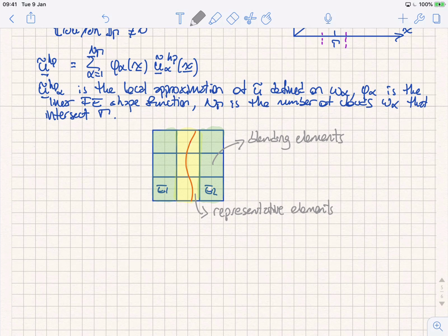That means that it's trying to reproduce some behavior in the representative element that has the discontinuity, but at the same time is connected to another cloud where there is no discontinuity. You understand this idea? That basically means that depending on the enrichment function that we use, there may be some issues in blending elements, right? So some enrichment functions are going to work, some are not going to work, or they are going to work, but our convergence rate is going to be reduced.